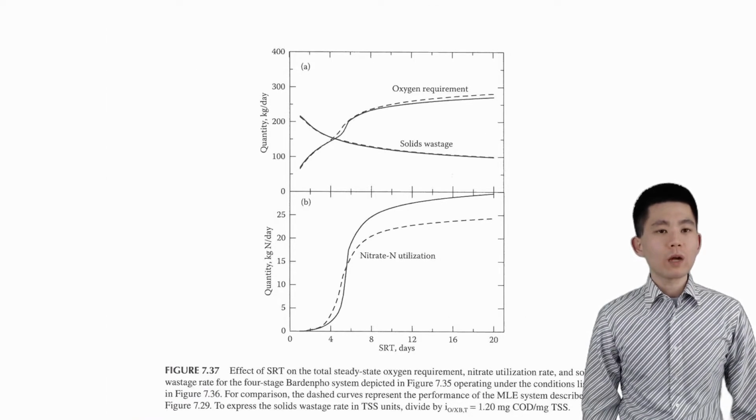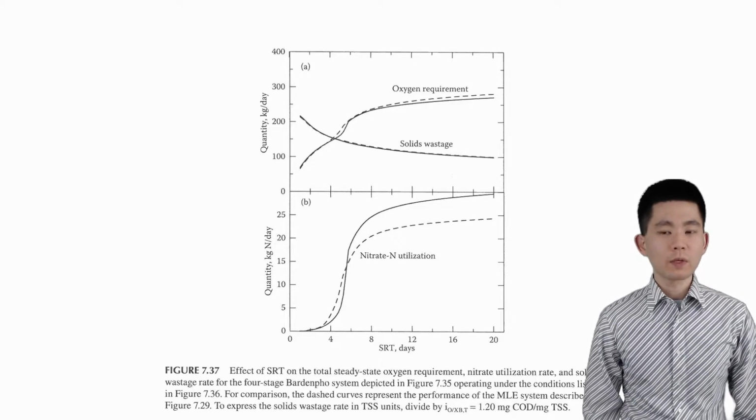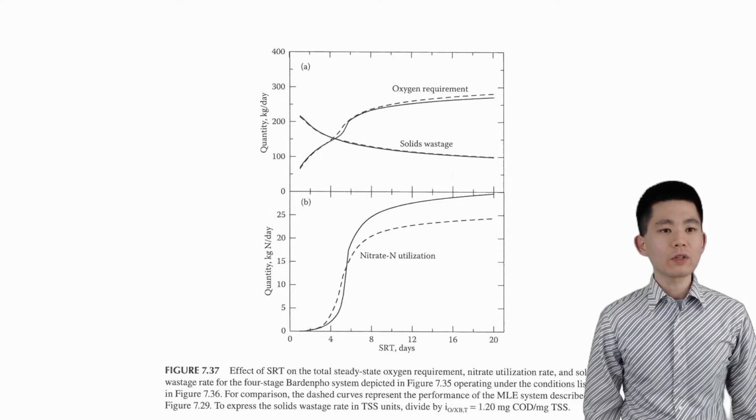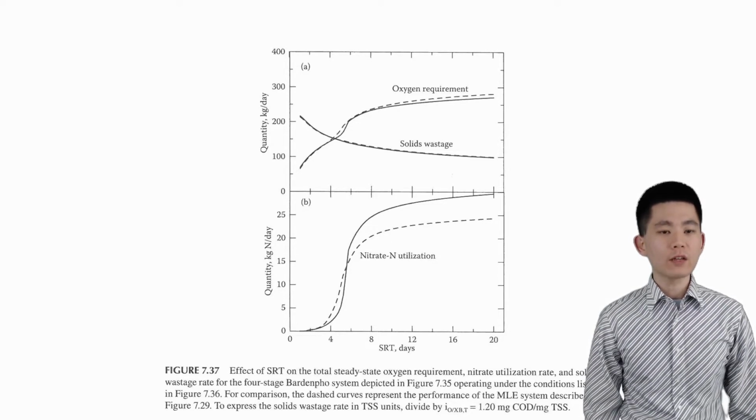The oxygen requirement and the solid wastage rate of the four-stage Bardenpho system are also very similar to the MLE system. The four-stage Bardenpho system shows a slightly lower oxygen requirement, possibly because of the further denitrification.